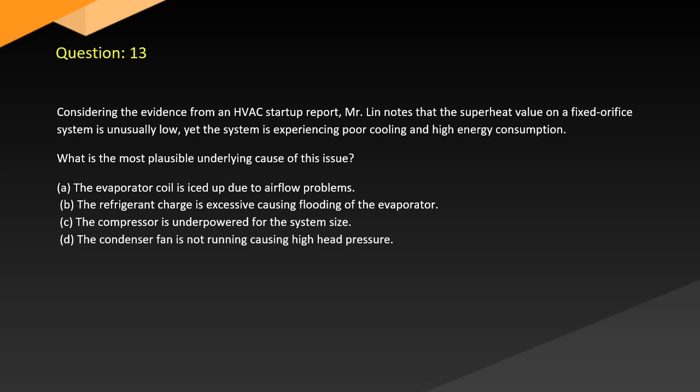A. The evaporator coil is iced up due to airflow problems. B. The refrigerant charge is excessive, causing flooding of the evaporator. C. The compressor is underpowered for the system size. D. The condenser fan is not running, causing high head pressure.